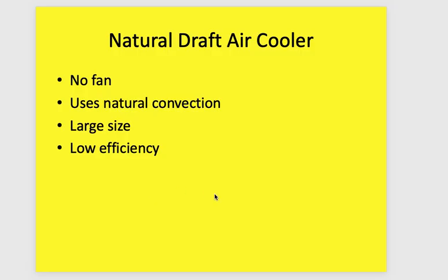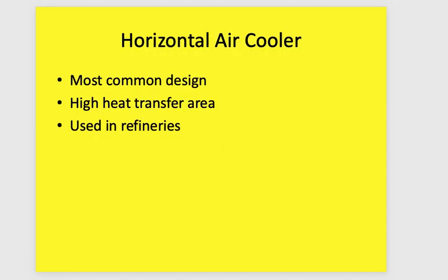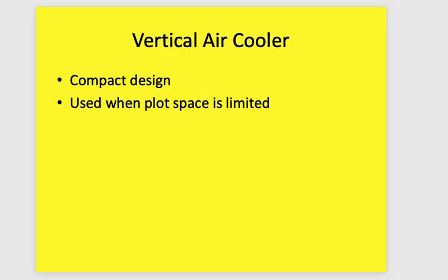Okay. There is the natural draft air cooler, no fan, using natural convection, large size and low efficiency. And in some cases the horizontal air cooler, the most common design, with high heat transfer area, used in refineries also. Okay, and there is in some cases a vertical air cooler, compact design, used when space is limited or your unit space is very limited.